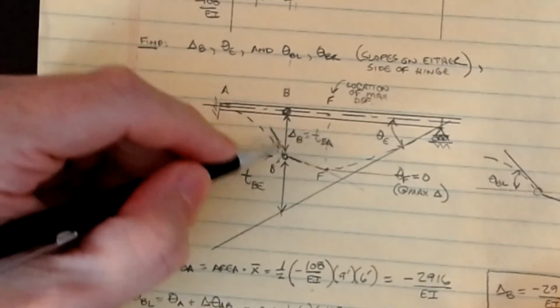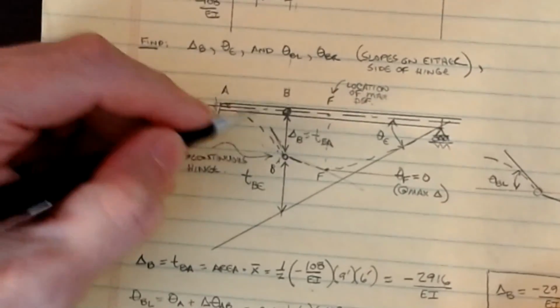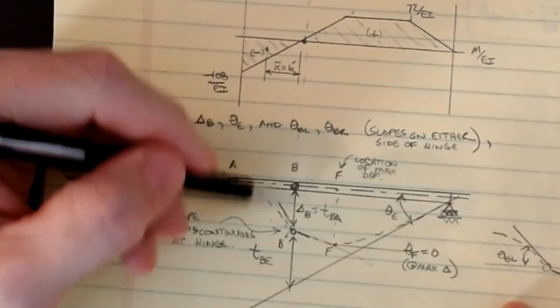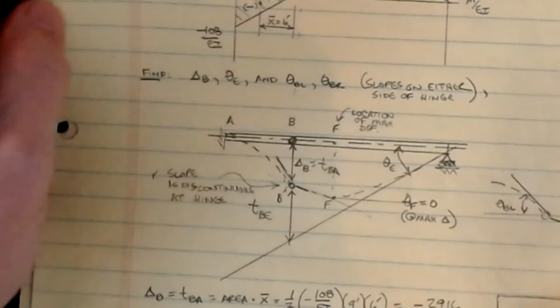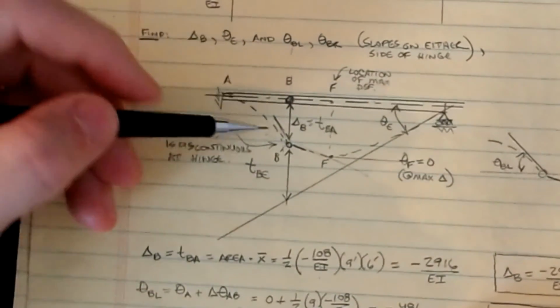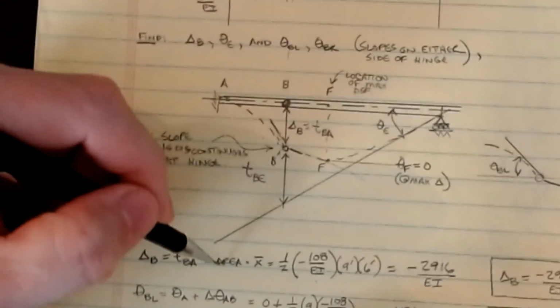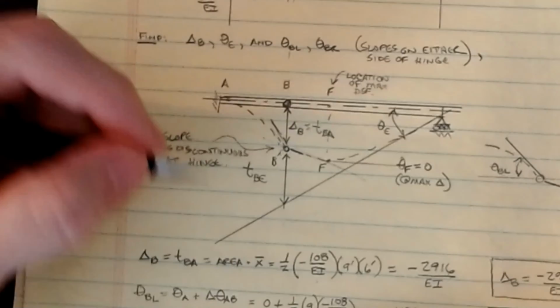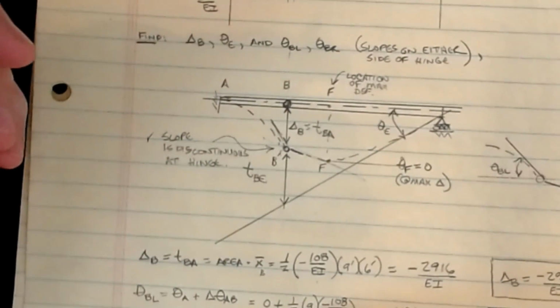So we're going to take this theta, and we're going to play with the tangent on the left. I have everything there because I have the moment diagram over that shape. And so we can find delta B, and that's simply the tangential deviation at B with respect to A. So if we do that, let's do our calculation then. This is the area between A and B, and this time we're looking for the tangential deviation, x bar B, so we're going to B at that location.